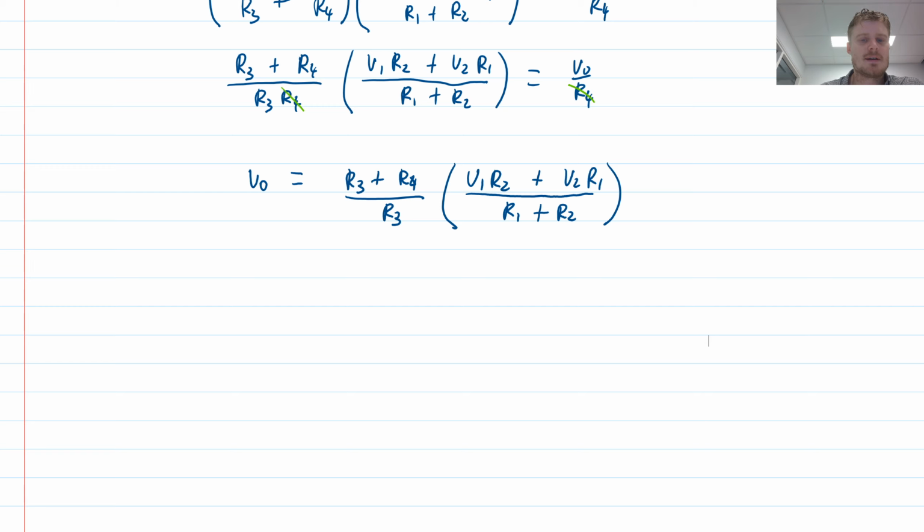So I guess we go through and pick some values in order to achieve the required characteristics. So if you want a larger contribution due to, let's say, V1, well, you could achieve that by having a larger value of R2 relative to R1, and therefore the terms here will be combined in such a way that there is a greater contribution due to V1, or whatever proportionality that you actually choose. So that's where these sorts of things would actually come in handy.